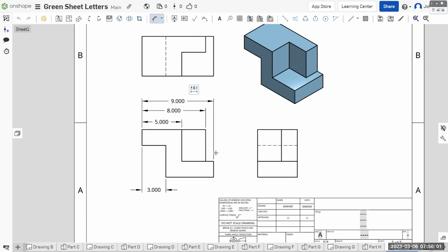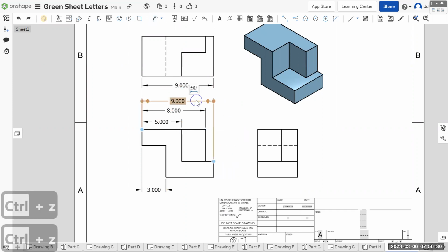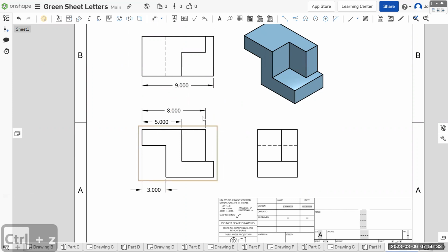No hidden line, everything. I'm not crazy about this long extension line, so I would say up here might be better. It's about the same. Having all the dimensions on the front is desirable. Long extension lines are not. But thinking ahead, for one of the height dimensions, we'll probably want to go there, and then we'd have something crossing. So I am going to just put it on the top view. And that's it for width.